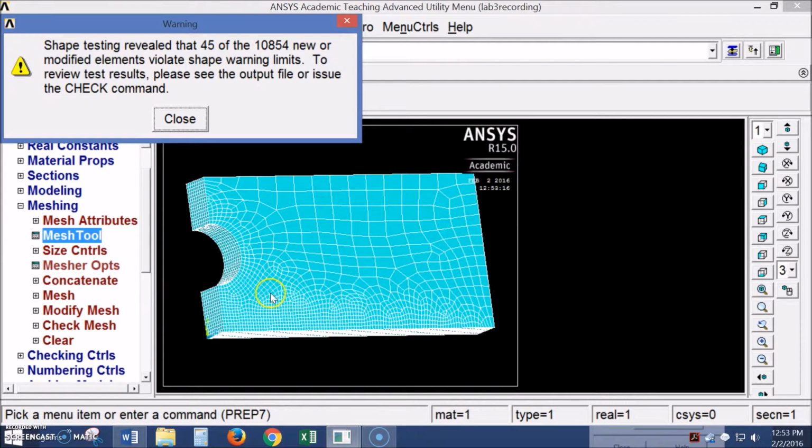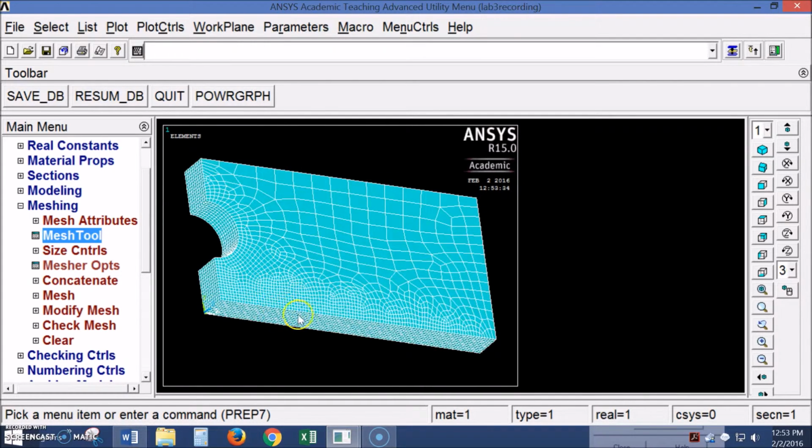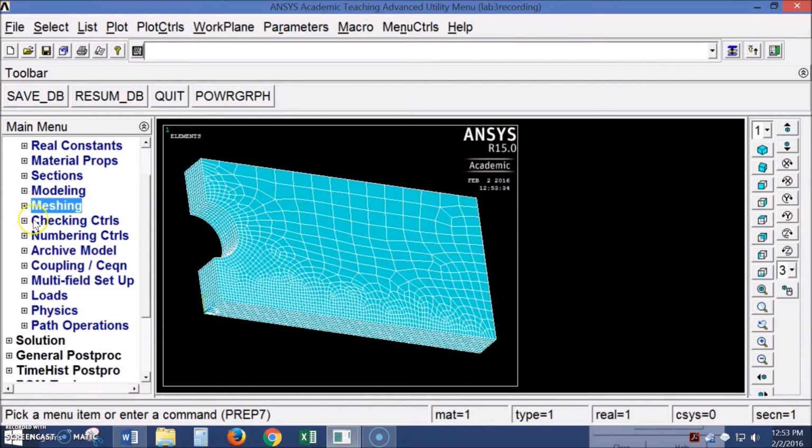And you'll notice that back here where we don't care about the stresses, we have larger elements, so we have less computing power going there, and all our computing power is being dedicated to the point where we know the stresses are going to be greater, which is along this stress concentration here. I probably could even ignore this side as well and just had it mesh these areas fine. So that's all the meshing we've done.